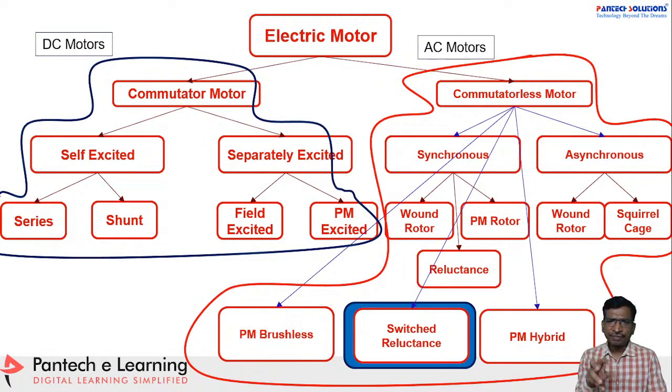So now you have to identify where the reluctance is very low. Out of two or three coils, if one coil has a very low reluctance and you switch that coil, the rotor will automatically align to that excited coil. Here you have two terms, aligned position and unaligned position. We will discuss them in detail. So please try to engage with the entire session.